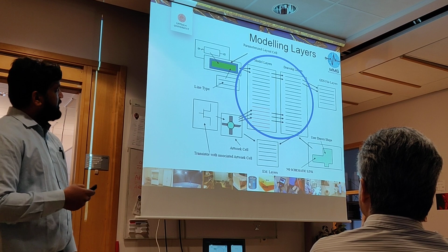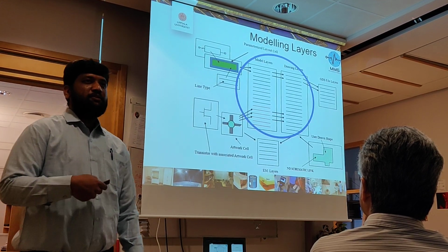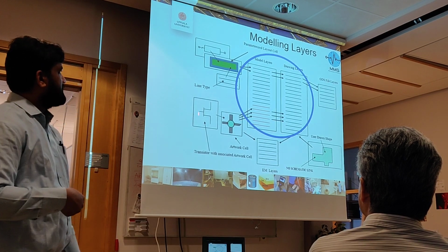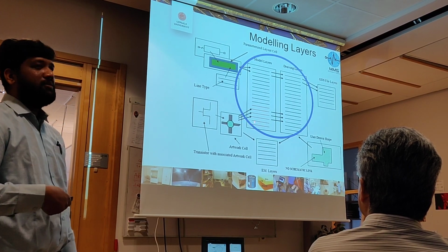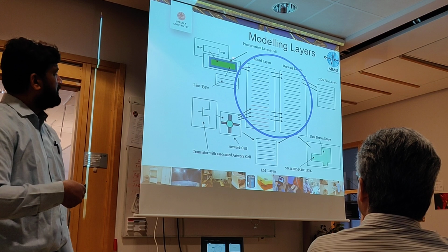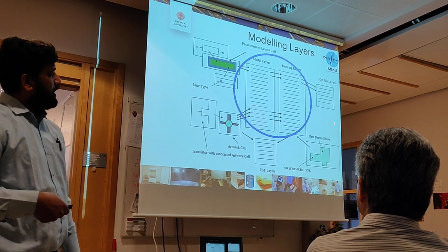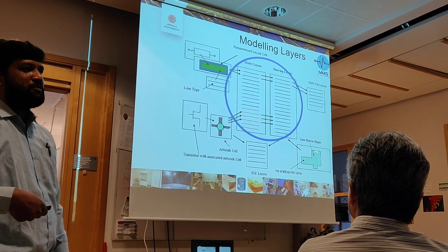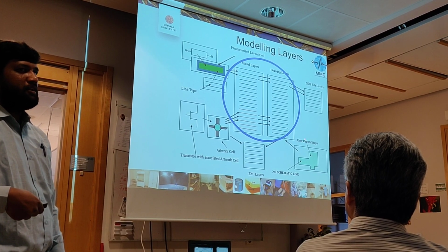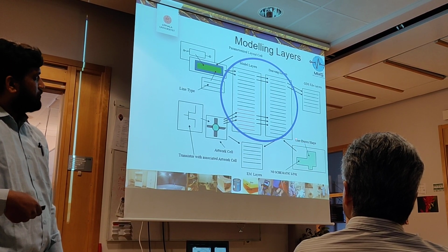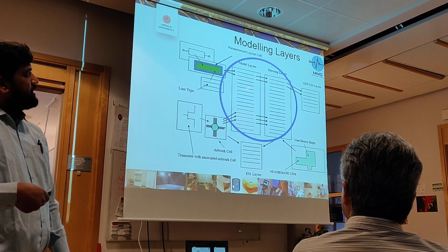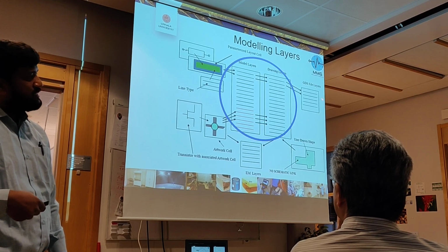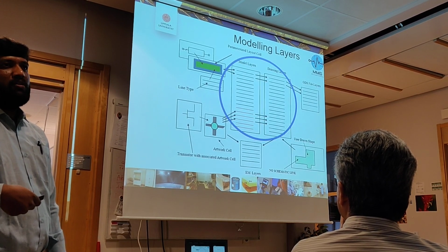And I just want to highlight this one. Whenever you are working with any of the tools, especially EDA tools, if you just drag and drop, in a schematic it looks like this. If you download from the internet, the art style will look like this, lines will look like this, and after drawing there is no schematic link, meaning many times it will show some different color. If you do not trust that tool, if the interaction between the drawing layer and model layer is not proper, then this GDS file will end up with a wrong Gerber file.